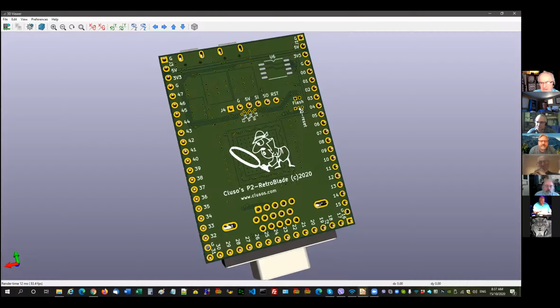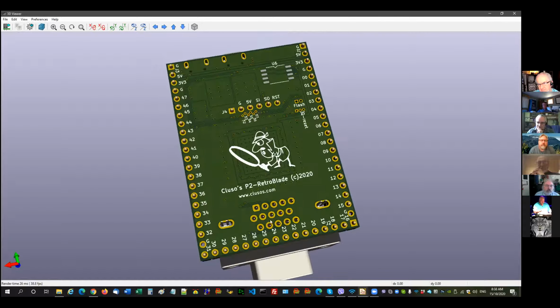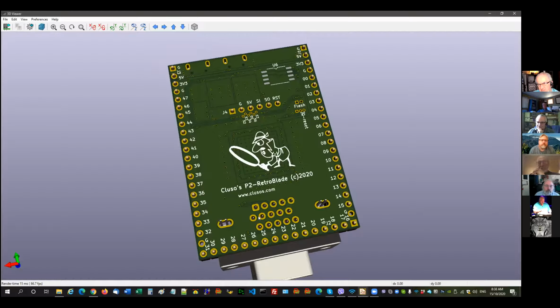This is your link for using the transistor reset or if you're going to use a prop plug. You can see how my VGA port overlays the top of this group of pin headers here. So if you extend them down under the board, you can leave them in and have access to them.